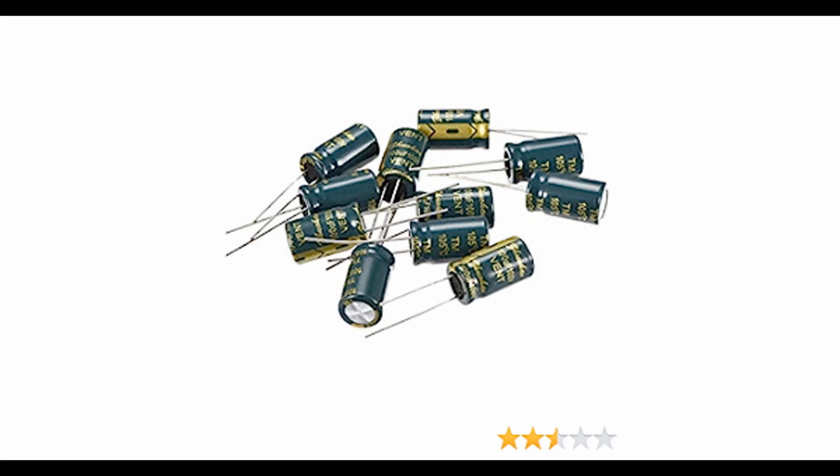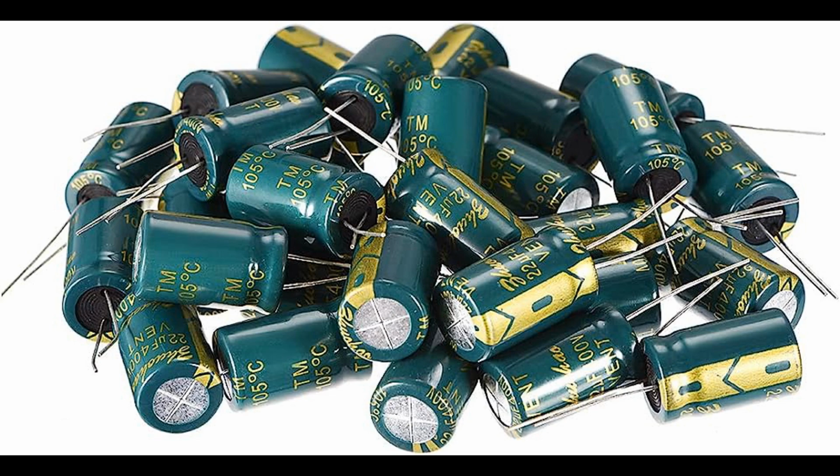Applications. Polarized capacitors, especially electrolytic capacitors, are commonly used in applications that require higher capacitance values and the ability to handle relatively high voltages. They are widely used in power supply filtering, audio systems, motor drives, lighting ballasts, and other electronic applications where larger capacitance values are needed. It is crucial to follow the manufacturer's guidelines and markings on polarized capacitors to ensure correct polarity during installation. When using polarized capacitors, always double-check the capacitor's polarity and connect it accordingly to prevent damage and ensure proper functioning of the circuit.